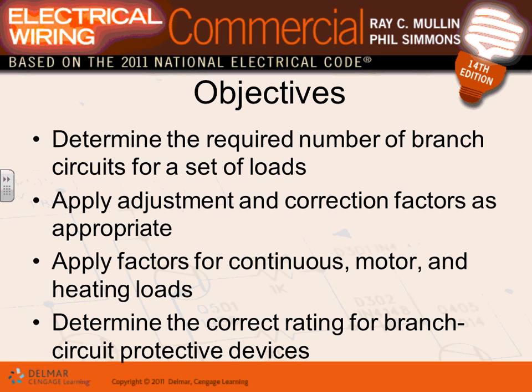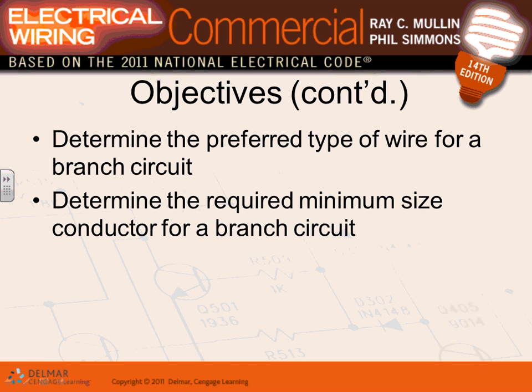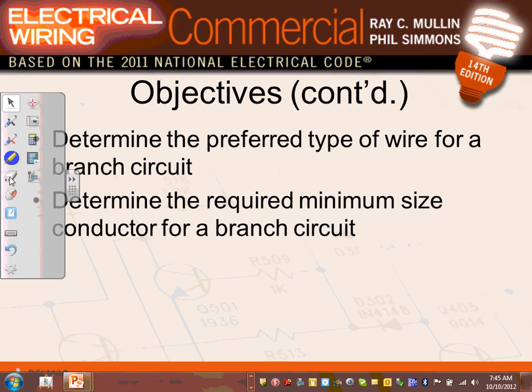When we have a branch circuit for a motor, you guys have done it with me last quarter and this quarter. What do we do? It's a continuous load. What do you do with it? 1.25. And the same thing, overcurrent. Every branch circuit must start and end with an overcurrent protection device.